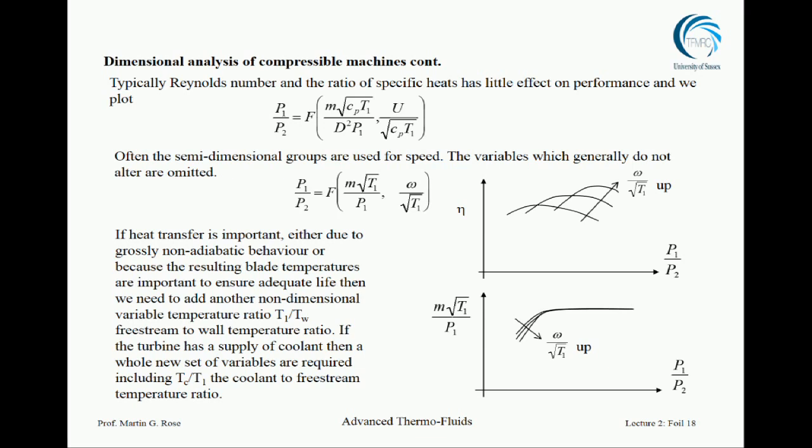The plane does have thrust reversers, so it can make the engine thrust go backwards. That's already configured in there, but you can't use it when the plane is stationary on the ground. You can't use it in that environment because it creates massive levels of turbulence and scouring, and will move anything that's on the ground and blow it around in front of it.